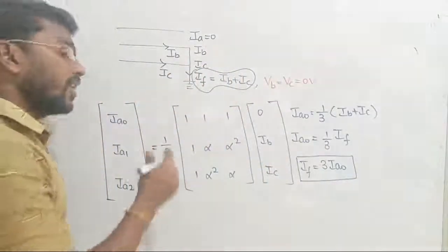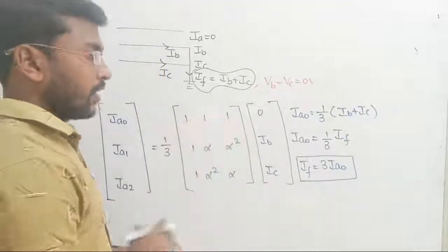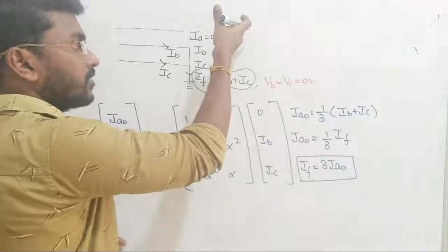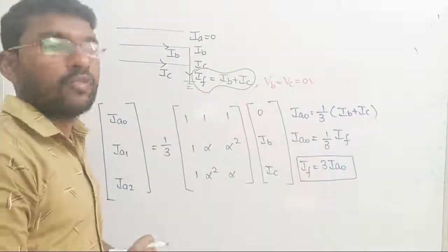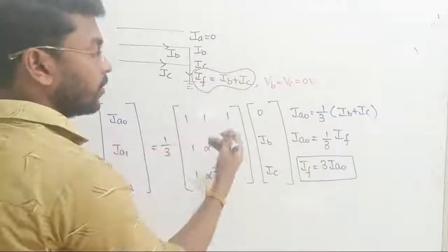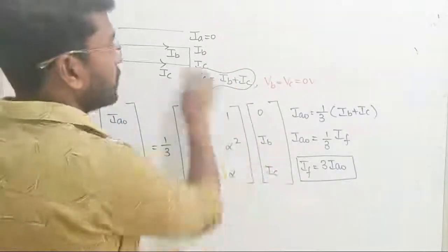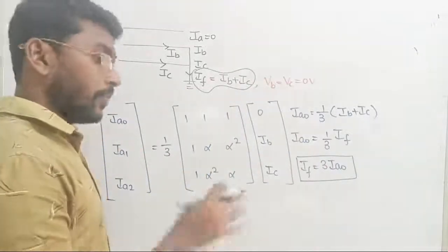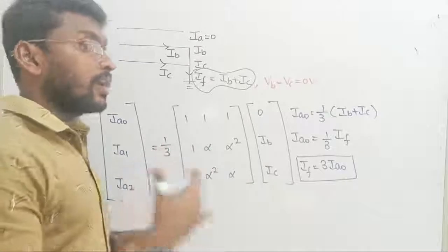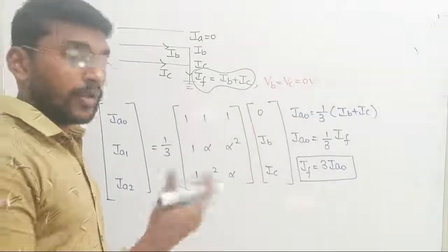In case of a double line to ground fault, we are just observing, guys. I am not doing anything here. I have the matrix. I am substituting whichever information I am getting here. That is what we are going to do in our SCADA also. When a fault happens, you will update that data. This is the matrix calculation. For our example, on paper, we are taking just a single line and doing these manual calculations. From your exam point of view, in your network there may be 100 buses, and all the data should be manipulated by your matrix. That is powerful analysis.